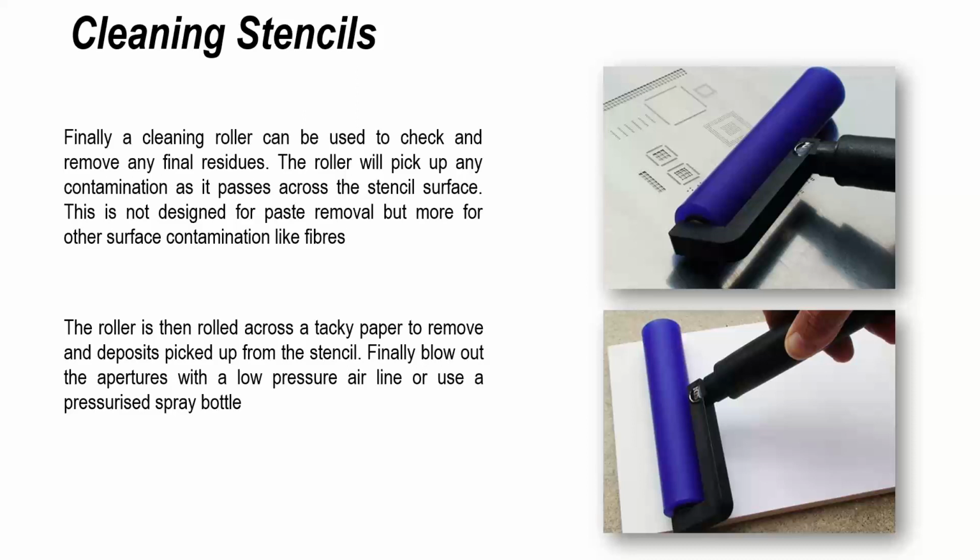So again, rolling over with a sticky roller, as I illustrate in this example, first of all, and then transferring it to a tacky sheet allows you to assess, or not the case, whether there is any residues on the surface. And these tacky rollers tend to be used on PCBs to pick up fiberglass residues or fiberglass resin, and can be used as part of an inline process.